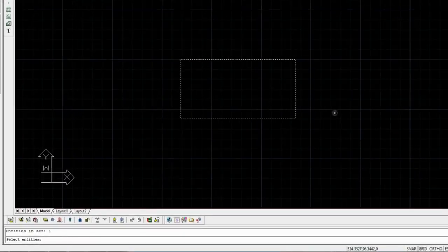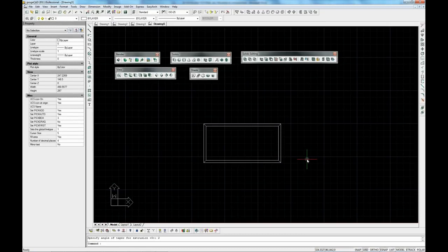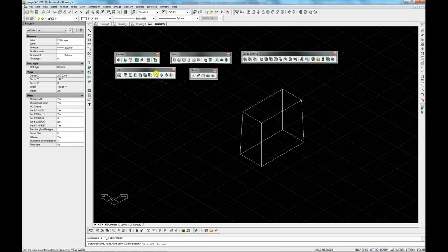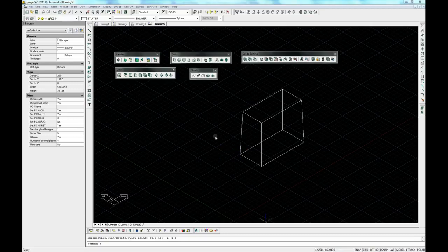The taper can provide designers with the basic draft and the angle for the part if we are designing plastic parts for molding. Then we enter an angle 2. First, you can see from this part, the top part of the shape, it is slightly tapering.